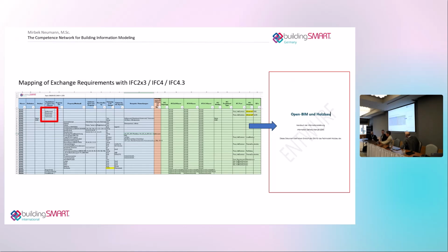We don't need any dead-end classification that everyone will be assigning to any model through bSDD APIs. At the end, if you don't map it, the machine, in that case CAD software, will realize, oh, okay, we have a default thing, it will be again IfcBuildingElementProxy. We would have a whole bunch of building element proxies classified according to bSDD, but we should avoid that.